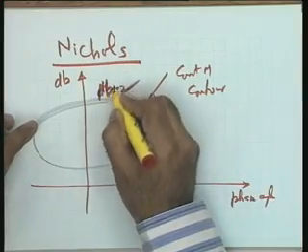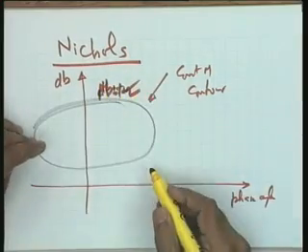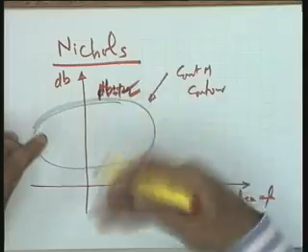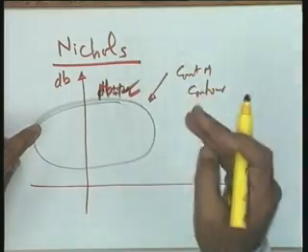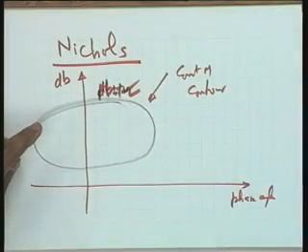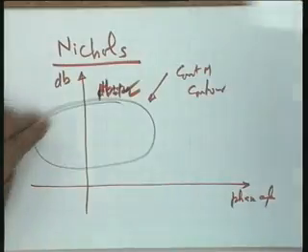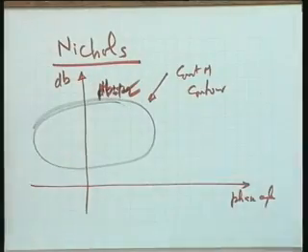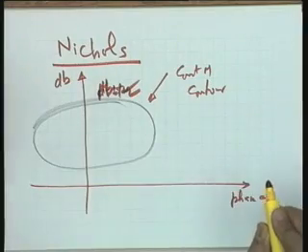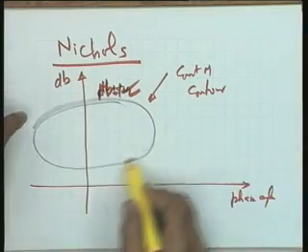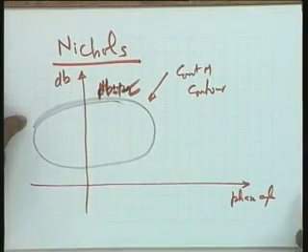M is equal to 1, it corresponds to M is equal to 1.2. So, it means if you want to convert in dB, it will be 20 log 1.2 naturally. So, this circle corresponding to M is equal to 1.2 has been translated here. Okay, let us not convert into dB, let me write it M is equal to 1.2, does not matter, but all these values are dB versus phase angle.